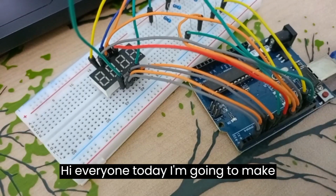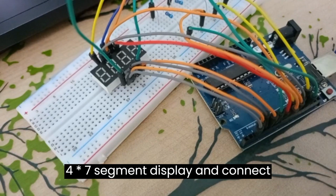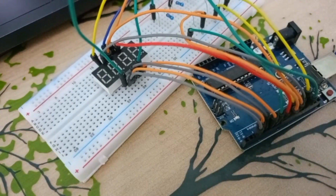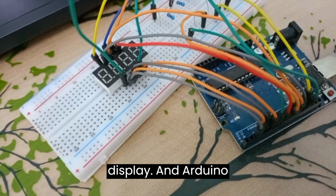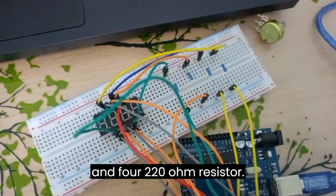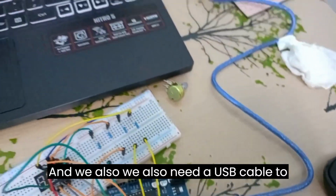Hi everyone, today I'm going to make a 4x7 segment display and connect it to the Arduino board to display my information. The things we need are a 4x7 segment display, an Arduino board, some jumper wires, and four 220 ohm resistors. We also need a USB cable to connect to the laptop.